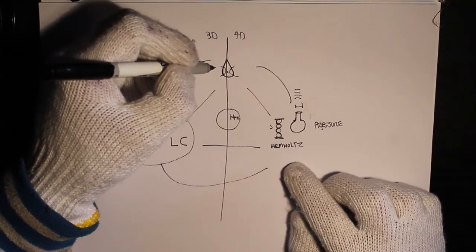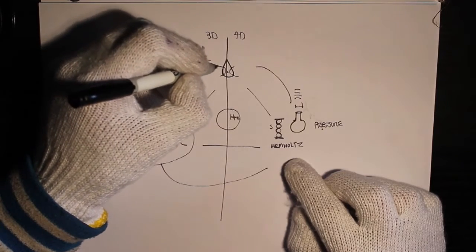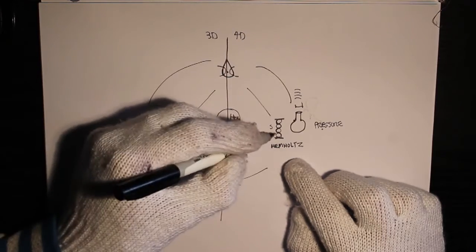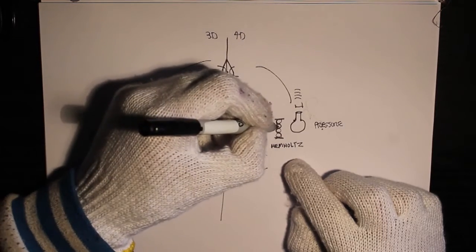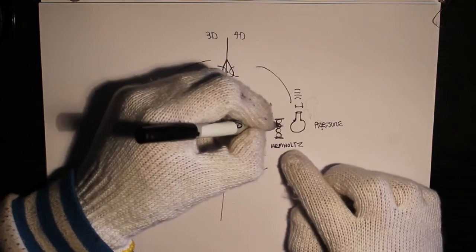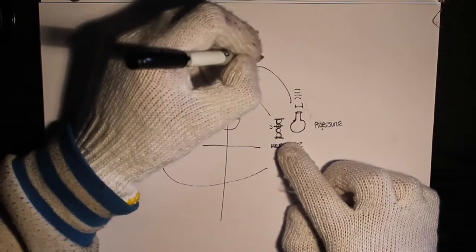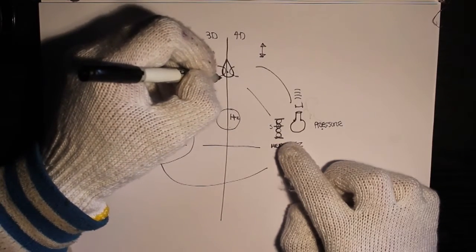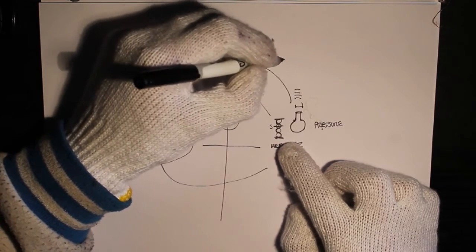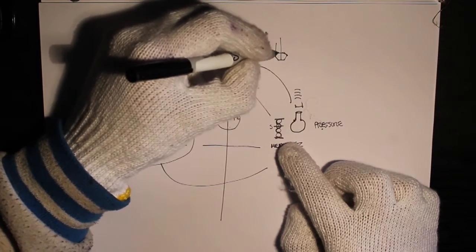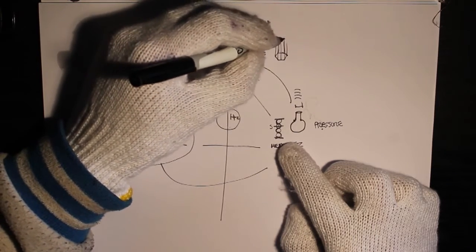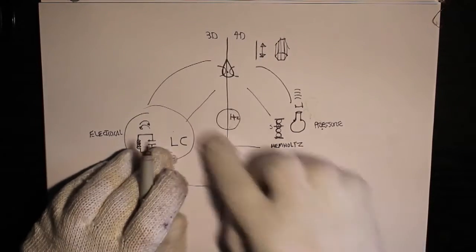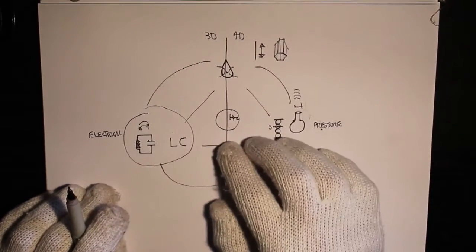And it doesn't oscillate like a normal crystal. It's not electrically connected at all. There are no wires going to it. It gets its oscillations from this system, the pressure wave, the standing waves. The quartz is over the standing waves, and it oscillates, which we'll get to, vertically, on a vertical axis only. The crystal is cut on its z-axis, and it's a quartz crystal that oscillates vertically. The pressure runs up and down the system only. So basically, that's very important to understand, because that explains how the whole system oscillates.